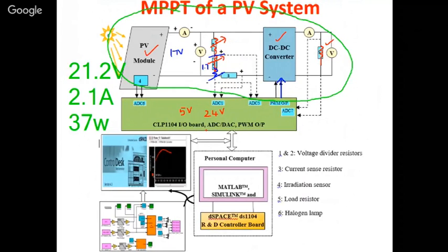Still, at our laboratory, we thought not to give high voltage. That's why we dropped a larger voltage at this upper resistor and only a small voltage remained. I'll show you, we did only 0.17. For the very safer side, we did 0.17 because even if a short or something occurs, our controller will burn out. So we were very careful. If you want, 1.7 is also not a big problem because most controllers still allow 20 volts, and nothing will happen to the controller.